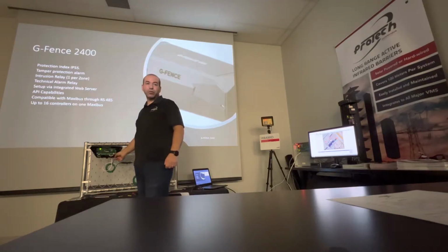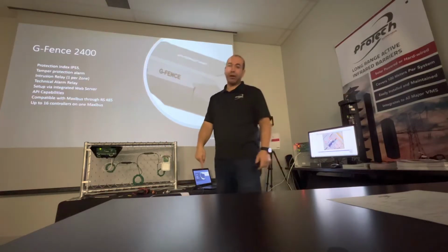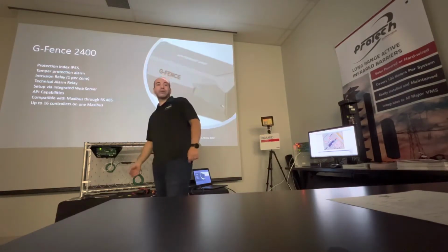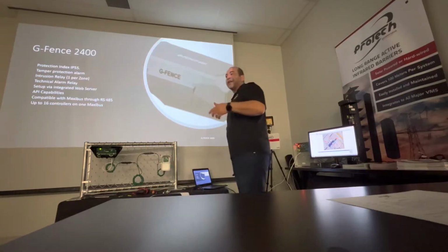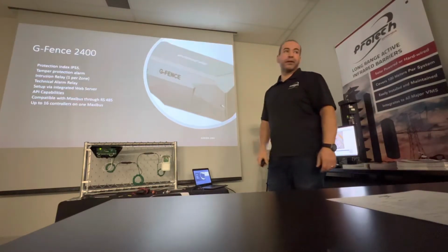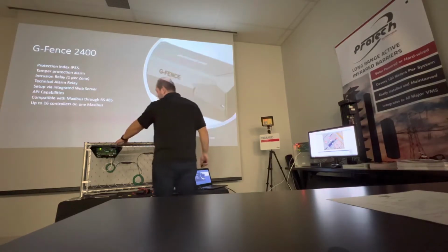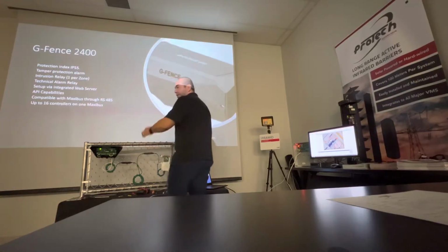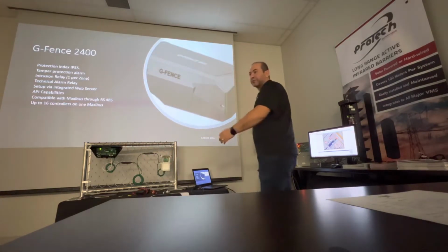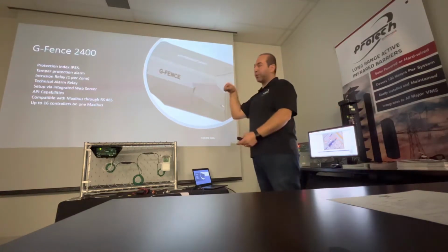So ground, it will be like a big metal rod inside the ground to make a real ground on it, because we need to avoid any storms, any problem, to protect the equipment itself, the control board. So even if you use more than one control unit, each ground will be independent with one cable. It could be PVC pipe inside and then going with the rod.